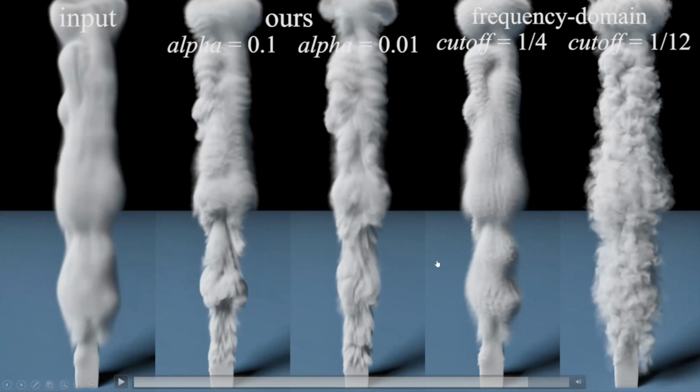And for the frequency domain method, this method also has a single parameter, that is a cutoff frequency shown here. So we need to choose an appropriate parameter for this cutoff frequency. If we choose an inappropriate parameter, in this case 1/4, the result is not very realistic. But if we choose an appropriate parameter, in this case 1/12, then the result seems the best among these four.